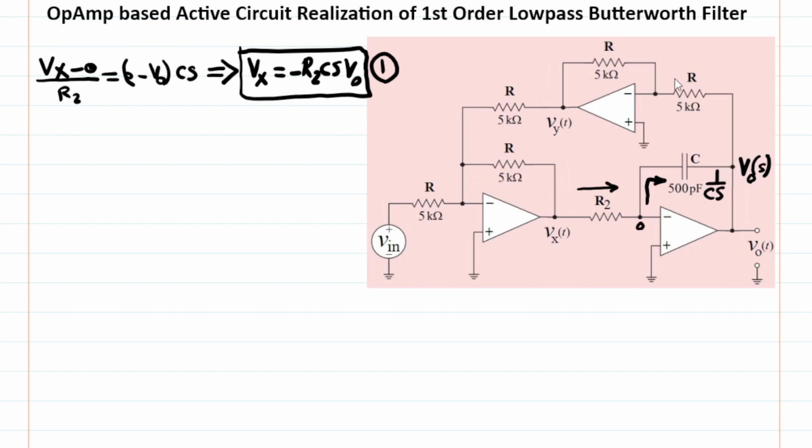Now, let's follow this feedback route here. So it's an ideal op-amp, and we know it's in negative feedback loop, not saturated. So whatever voltage appears here, the voltage that appears at Vy is just minus R divided by R times this voltage. So Vy, I mean, you can just again write the same KCL idea. So here is 0 volt, here is 0. So whatever current flows this way, there is no way for that current to go except flowing this way as well.